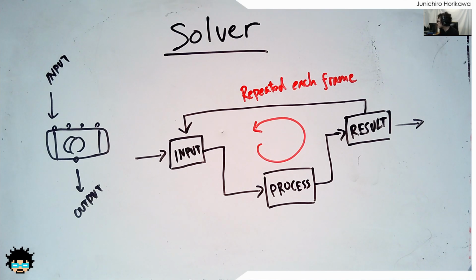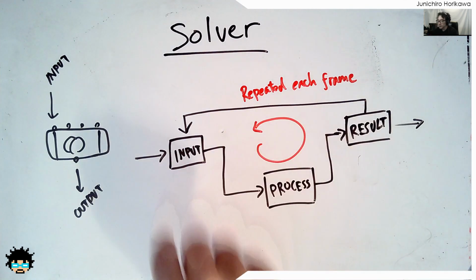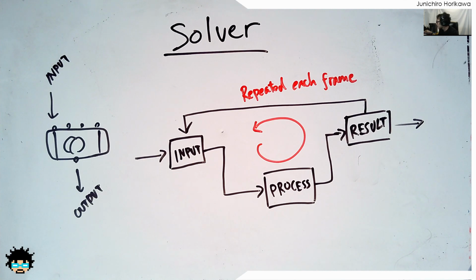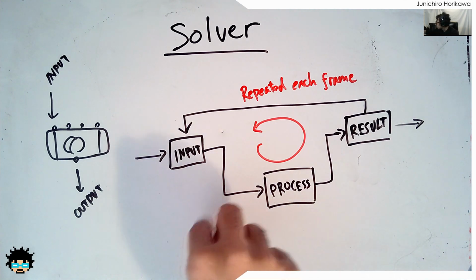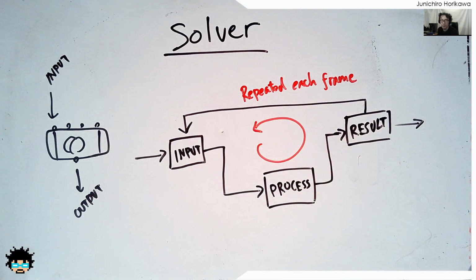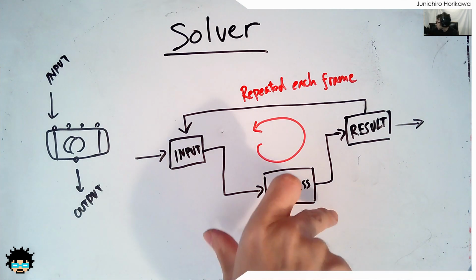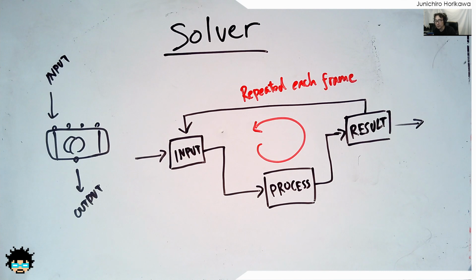If you use a for each loop node in Houdini, you can do similar things in one frame. But if you want to create an animation based on this loop, then using a solver is the way to go. And the benefit of using solver to create your own system instead of using something like a DOP network is the flexibility of the result you can create. And combining this solver system together with the VEX coding, you can almost do anything. You can even try to mimic the dynamics using the SOP solver, if you know the algorithm.